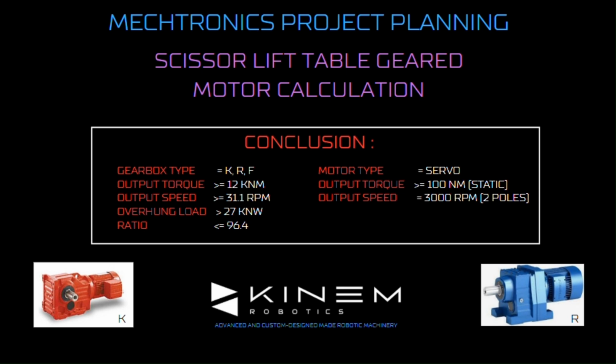Motor type, servo. Output torque, bigger or equal to 100 Nm, static. Output speed, equal to 3000 RPM, 2-pole motor.